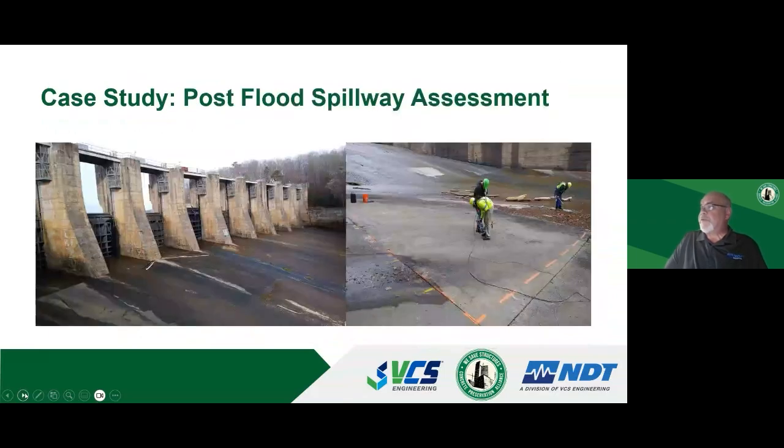Another post-flood spillway, a much larger one, had a couple of sections that were power washed in a phased approach. We quantified the condition of the concrete as well as the voiding underneath it. Some parts of the spillway were founded on rock, some were on rubble, and some were on voiding.